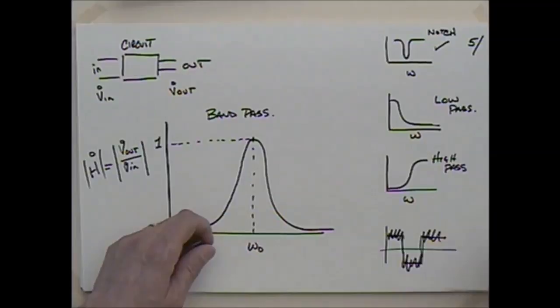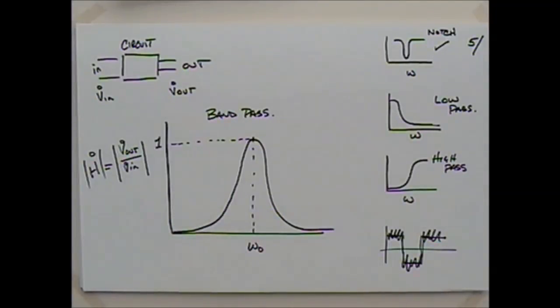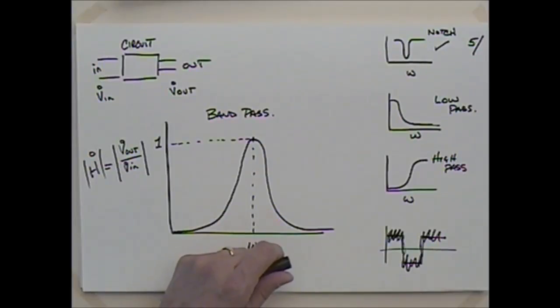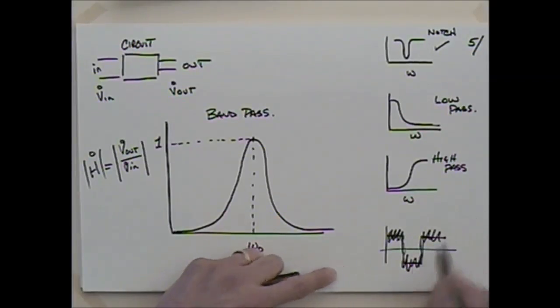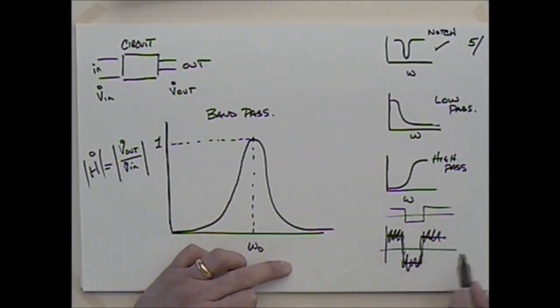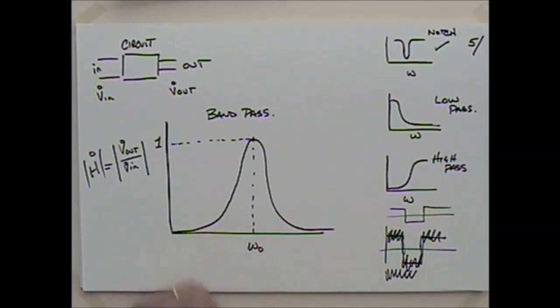If it's a low pass, it keeps the low frequency, which is the square wave, and it gets rid of this high frequency that's the noise. Right. You have two waves here. You have the square wave that is a low frequency event, and then you have the noise that is a very high frequency event. So you're going to try and get rid of that high frequency.